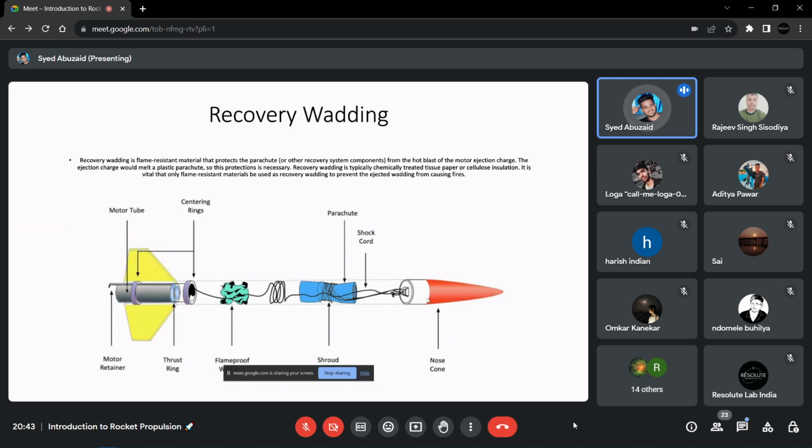They are using a solid propulsion system because it provides a very high amount of thrust, but it cannot provide enough velocity because the mass inside the solid fuel is very big. A big amount of mass, a big amount of molecules, provides enough thrust and produces enough force, but the mass flow velocity is less compared to the liquid propulsion system. So in the first stage, they are using a solid fuel rocket.